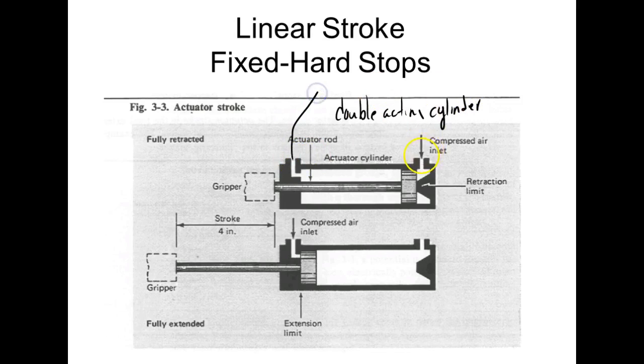Because what we do is we come up here and put pressure on one side, not on the same time. So if I put pressure into this side, it's going to cause this cylinder, the rod, we call that the rod. We call this the piston, by the way. We use a lot of terms that we do in automobiles. So the rod would push out, and then we call that extend. The rod would extend. Then what would I do? I would take this pressure off here, then I'd apply pressure right there, and then this is going to push that piston back in that direction, which is going to cause the rod to retract.